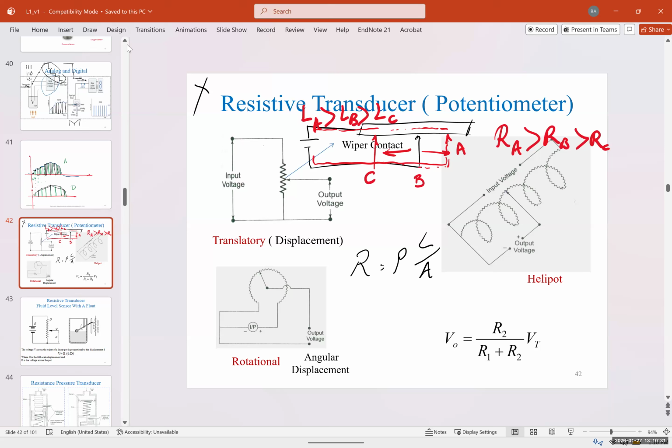And it's the same if you are using a radio and it has these round knobs. By changing this resistor, you're changing the RC and the filter, and you're shifting the filter, and you're picking a certain station, an FM station. Newer ones are using digital. They're not using any analog resistors and potentiometers, but these potentiometers are still in use in a lot of different applications as well. If you want to build a filter, it's going to be a great option. Any type of amplifier, if you need a variable resistor to control the gain of the amplifier, you can use a potentiometer.